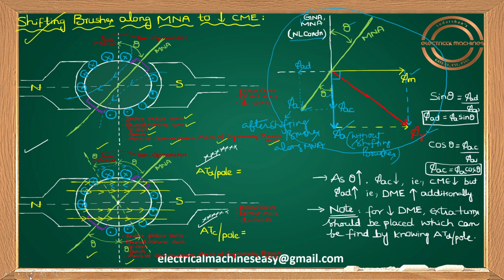If you want, you can check once again, please. In the right hand thumb rule, once again, your thumb is in the direction of armature current, which is out of the board. So the thumb should be out of the board, or out of the laptop screen. The direction of armature flux will be anti-clockwise. It will be like this. Anti-clockwise means it will be like this.